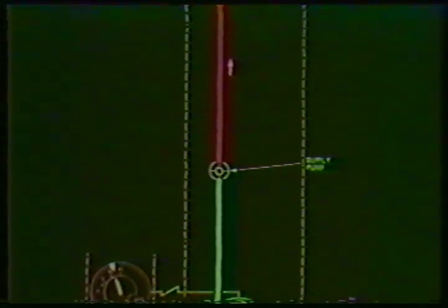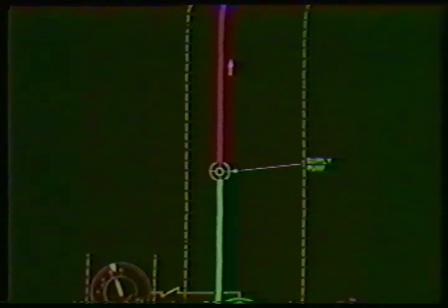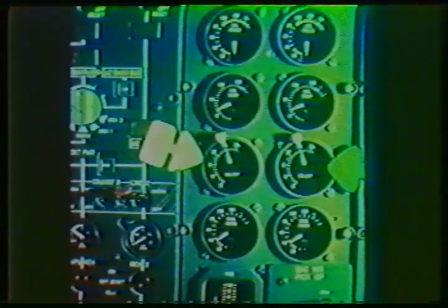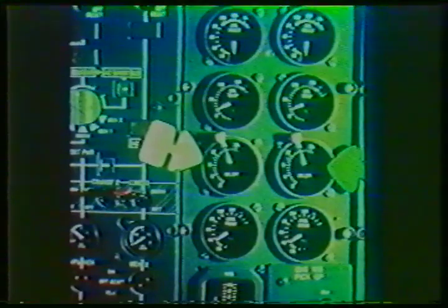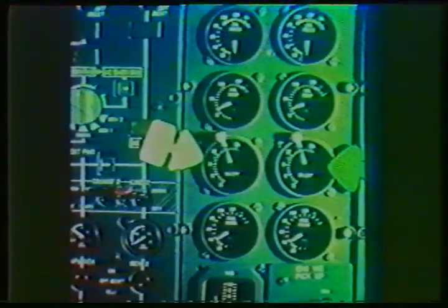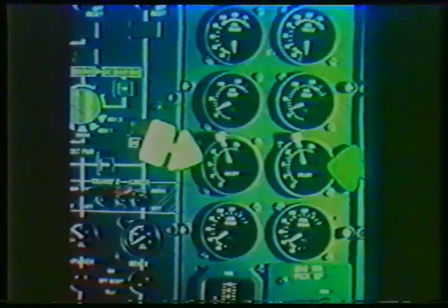The oil supply tank is on the right side of the engine with an access door in the fan cowl. The tank has a gravity fill cap and a dipstick in addition to a pressure fill port and a pressure fill overflow port. An oil quantity transmitter provides information to an oil quantity gauge on the second officer's panel. This tank supplies oil to the engine oil pump.